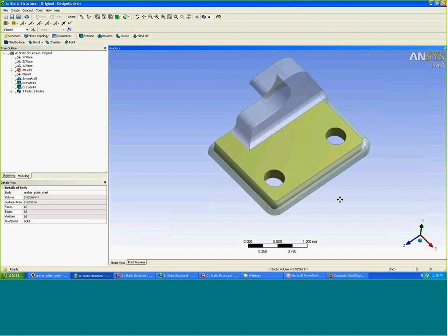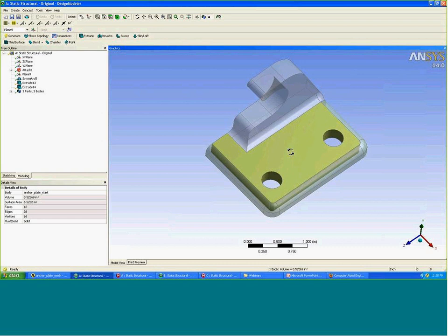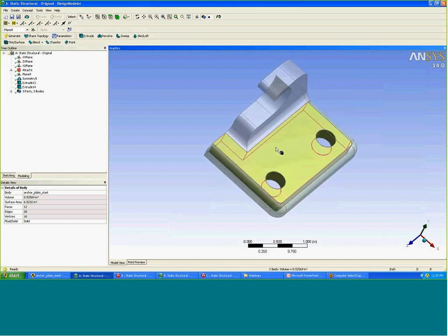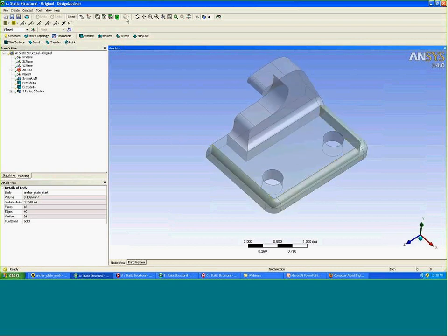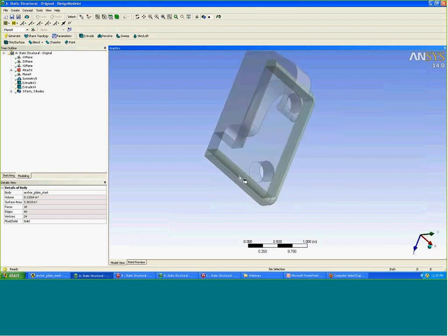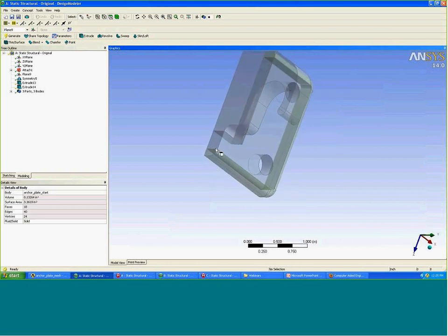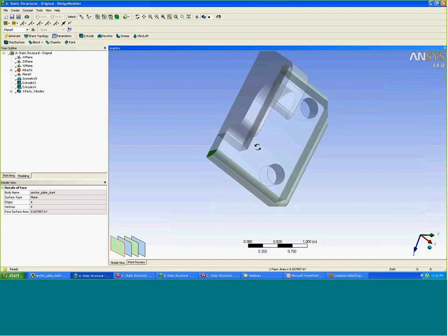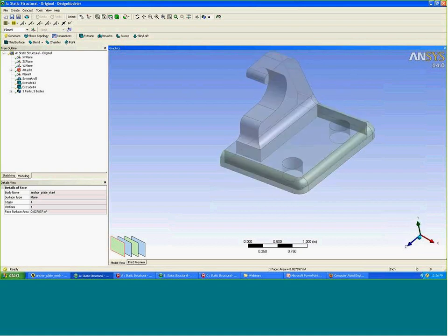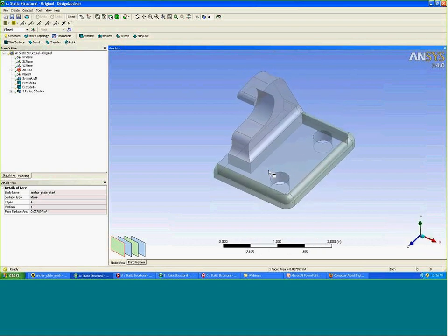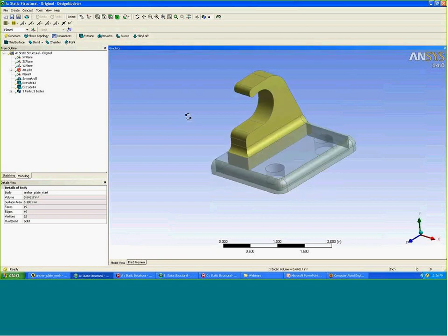On the base plate, I now have 2 sweepable bodies. So this one, the main area here, is very clearly sweepable, where I have a top face and a bottom face that are topologically exactly the same. But on the outside, however, it may not look exactly like it's sweepable. But it is actually sweepable because I have the same here as I do on the other end here, and I can sweep it all the way around the outside. Definitely 2 sweepable bodies here, but I have this chunky part up here that's not quite sweepable yet.